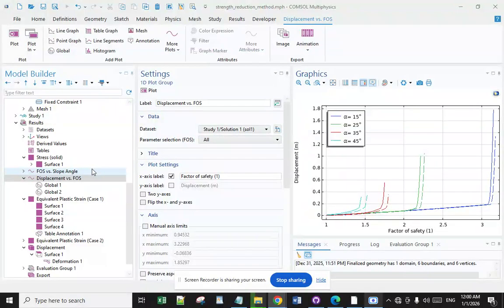And what are the key concepts? The definition: a measure of redundancy or margin against failure, showing how much over-designed something is for normal use. The next one is formula. Factor of safety is equal to ultimate strength or load divided by working stress or load.